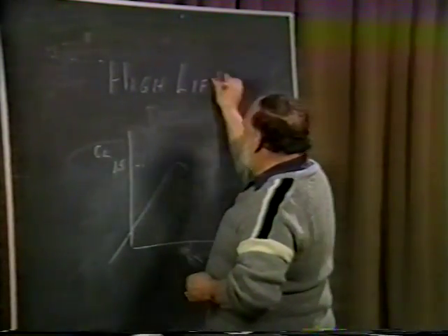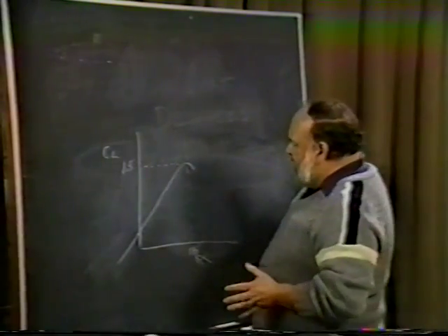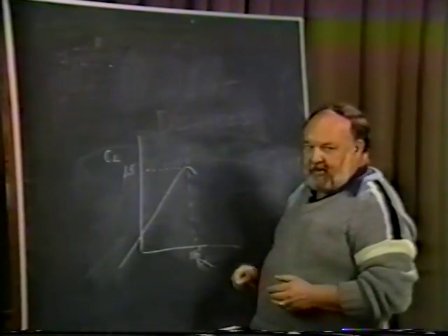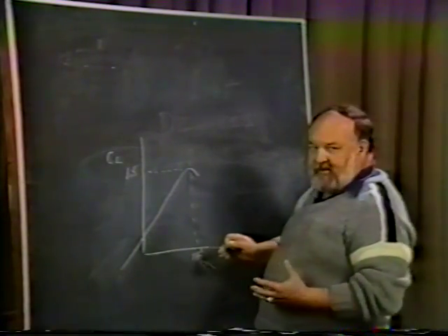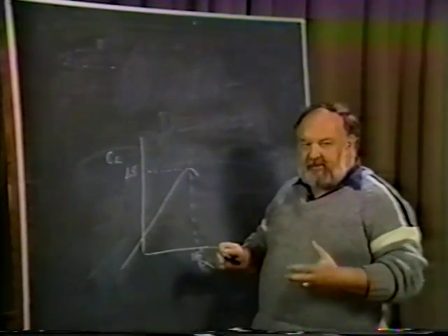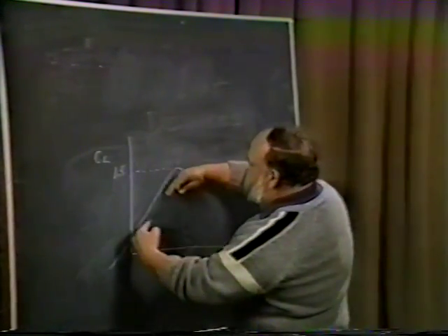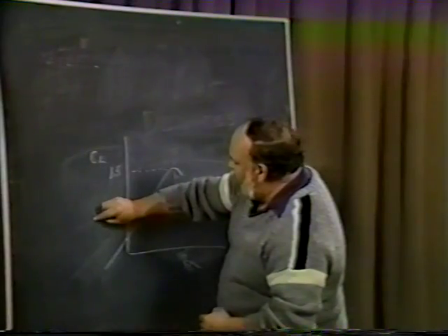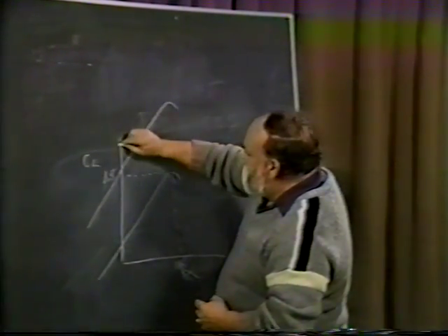I'm going to erase this portion up here to give a little bit more room, because what I really want to demonstrate is this. This is a plain ordinary wing section, and if we put flaps on it, trailing edge flaps of any type, split, single slotted, Fowler, whatever it might be, it basically lifts this curve up and moves it into a new section like this.